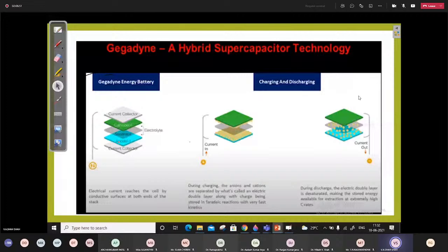The performance of a vehicle is determined by the following factors: cruising speed, gradability, and acceleration. These are the 3 factors which we need to consider. So let's say we have selected this as our driving cycle, and with that driving cycle and available vehicle data, we have calculated the power, and this is the power.